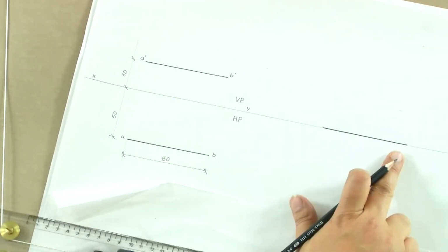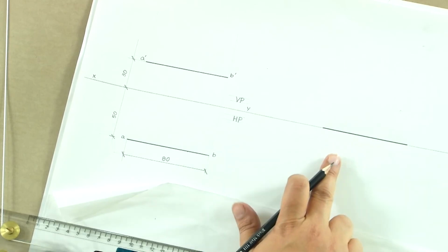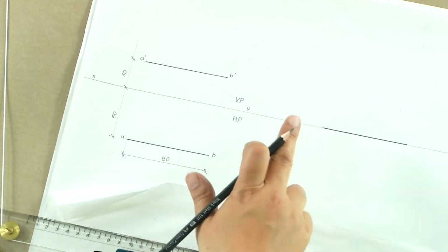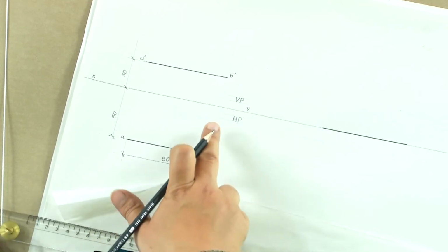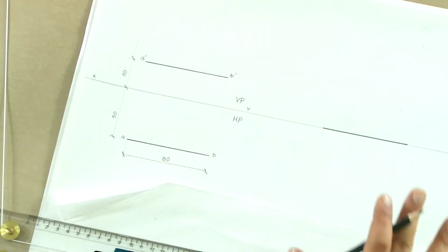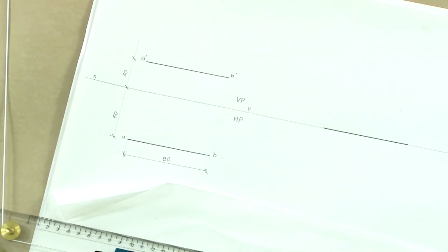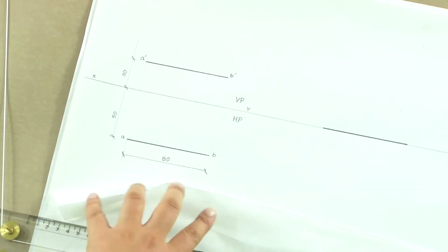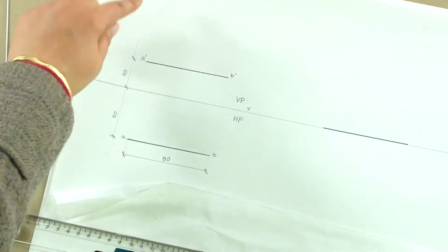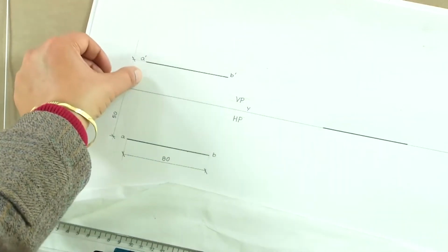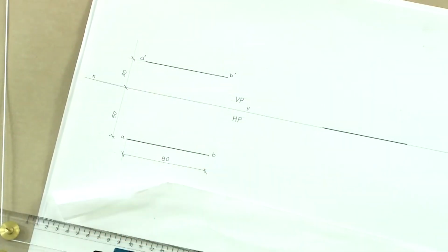That is the reason why I emphasize that the thicknesses of the reference line, the final object, the dimension line, and the projection lines should all be in the desired order. If you look at this drawing or the previous drawing, you would see that we always take these projectors to be very thin. They should not be seen.